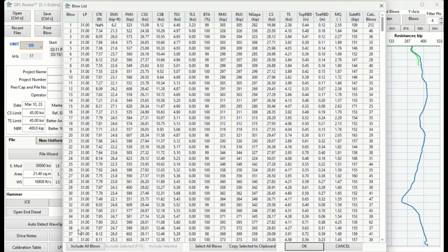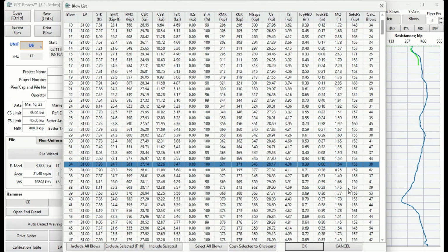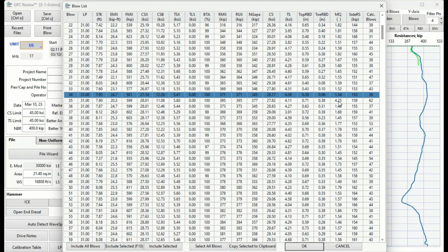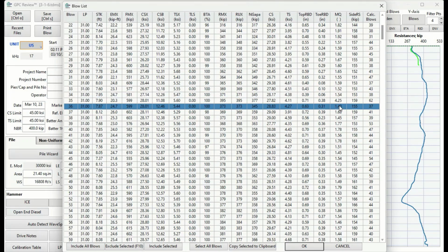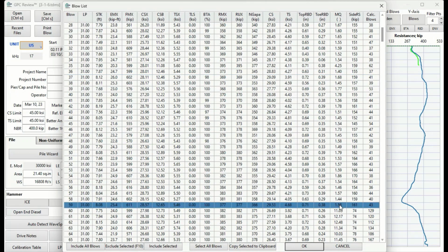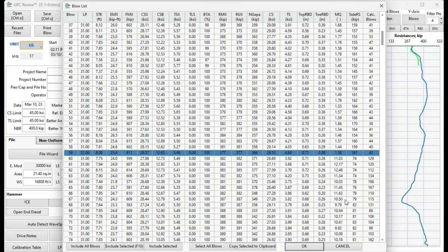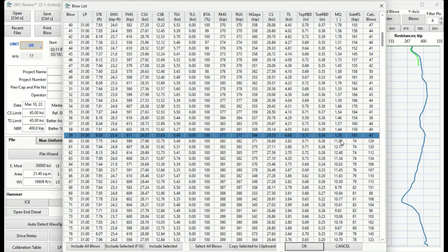And let's take a look. So 56 blows here, all match quality are good. So by looking at this, you see that it finished the... oh, actually one of the blows, the match quality is not that great, but then it is improving on the next blow. So it finished 59 actually. It finished 59's analysis there, and the last one that it ran, the match quality is 1.58, and the program hasn't gone to blow number 60 and so on and so forth yet.